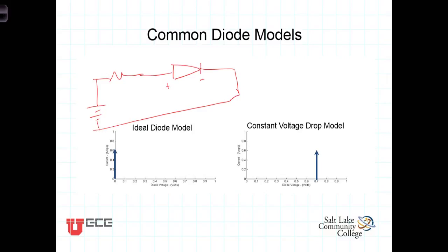Now for electronic diodes, the diodes that we'll be using generally speaking in the lab, it's a good estimate to just say, well, that's going to have a 0.7 of a volt drop. Those voltage drops are usually somewhere between about 0.5 volts and 0.75 or maybe 0.8 volts for typical signal type diodes. LEDs, on the other hand, light-emitting diodes, actually have a junction voltage up around 1.5 volts and sometimes as much as 2.5 volts, such that it takes an external voltage of 1.5 volts to 2.5 volts to get current flowing through the diode, or to get the diode into its conducting region.